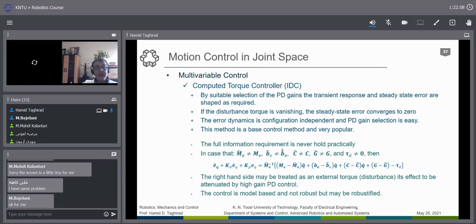So even if you do a very sophisticated identification process and a lot of work on the calibration of the robot, all the least squares methods we use for identification and calibration leave at least a small remaining error, because they are approximate methods for finding the parameters. And you saw in the last chapter that changing the configuration and also changing the frequency of the input will change the dynamic of the system.